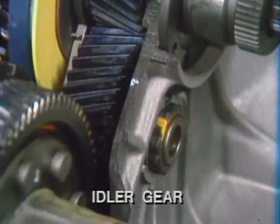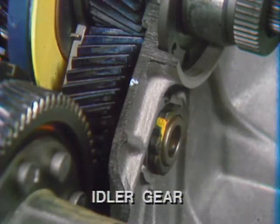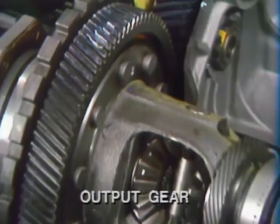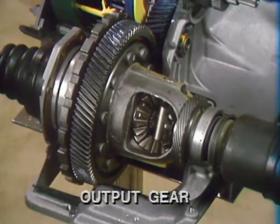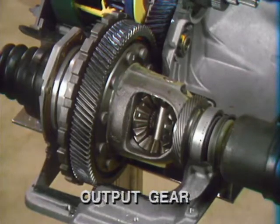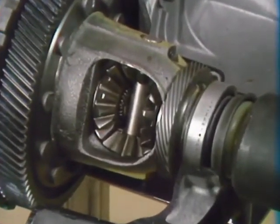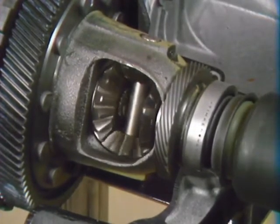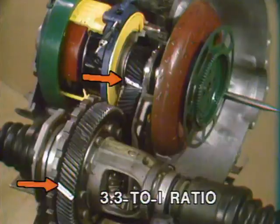The idler gear is supported on a shaft between 2 tapered roller bearings so that it meshes with the input gear. Its only purpose is to reverse the direction of power flow. The output gear is attached to the case of the differential, which also is supported in the transaxle by 2 tapered roller bearings. The differential works just like a rear axle differential, except it is part of the transaxle and it drives the front axle shafts.